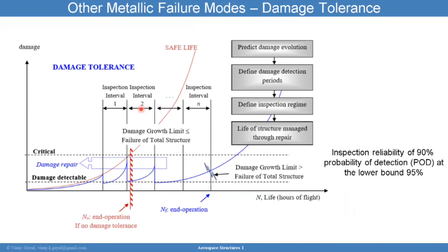For example, landing gear, because of the amount of impact loading it experiences during landing, will require a shorter inspection interval than the fuselage. An engine component, such as the blades of an engine, gets inspected regularly as well, because we don't want flaws that initiate at the root of those blades and cause failure.